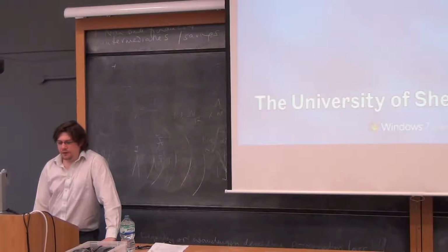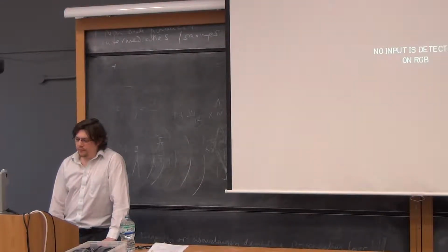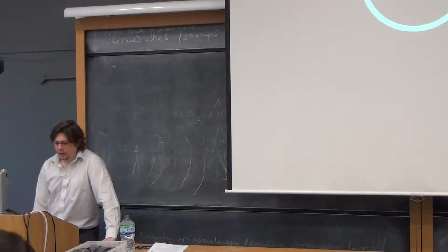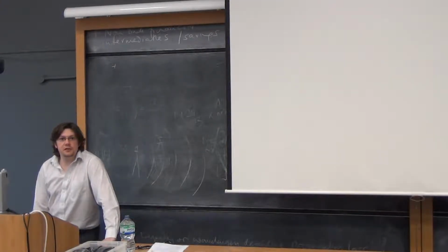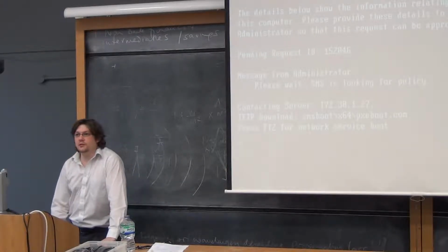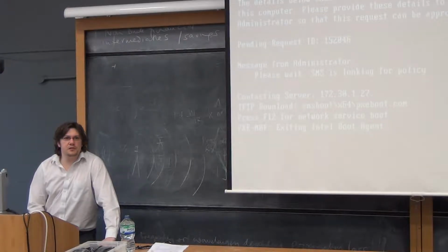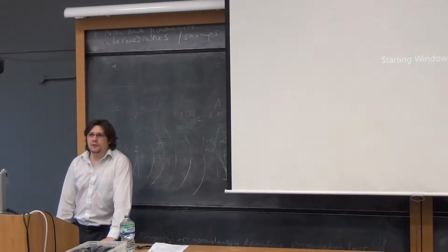Then I spent most of the second half of the lecture working towards a large signal model, and we had a large signal model for a bipolar transistor under all situations. We developed that further into a bipolar transistor which is switched on, and we said there are 2 saturation voltages, the base emitter saturation voltage and the collector emitter saturation voltage.